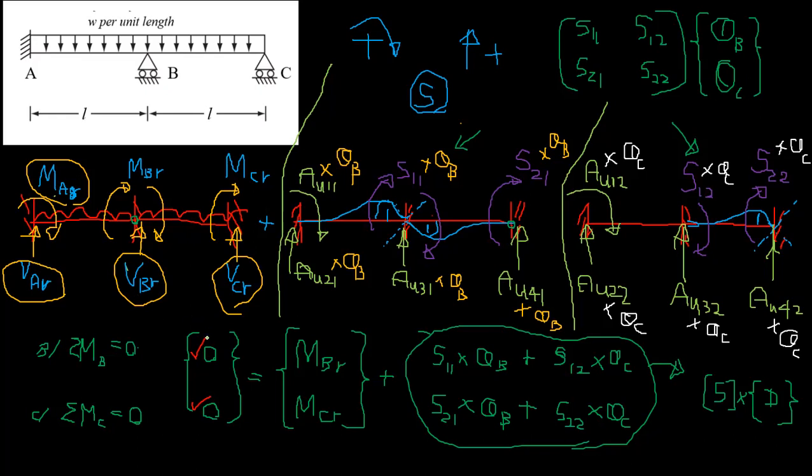So we are going to find the equilibrium at each joint where we consider the redundant displacements, right? Unknown displacements. And here you can see for this, you know, the equilibrium, the total bending moment is 0. The total bending moment about this point is 0. Why? It's not a fixed joint, so it does not restrain any rotations.